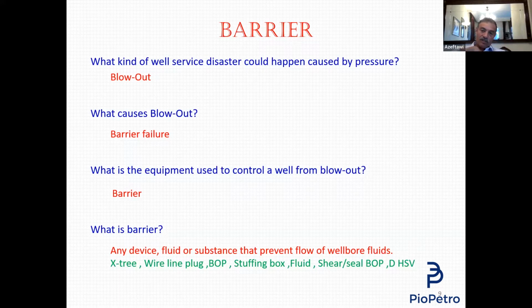And this device, the downhole safety valve, we can open and close by a control line from the landing nipple below all the way to the surface, where at the surface I have a control panel or a high pressure pump that can open and close this valve. All these devices you see written in green, I can use as a barrier that prevents the flow of hydrocarbons.